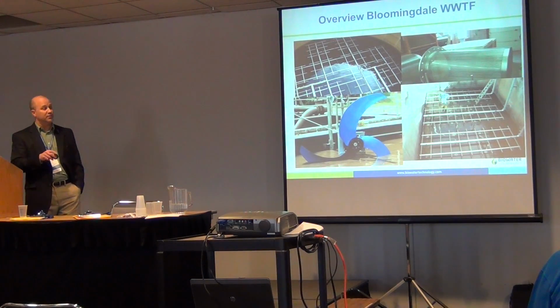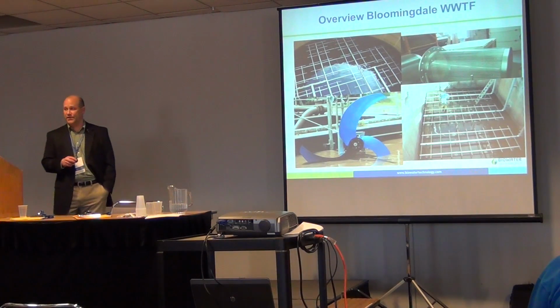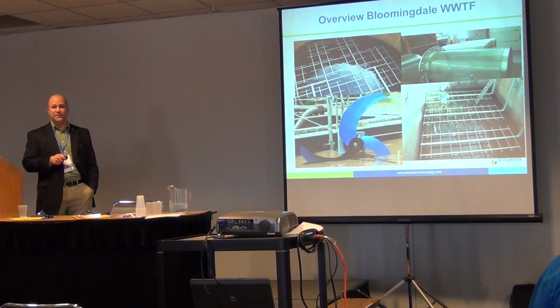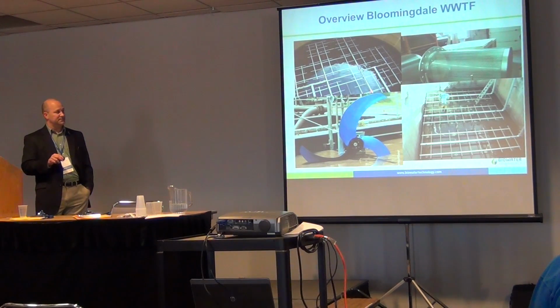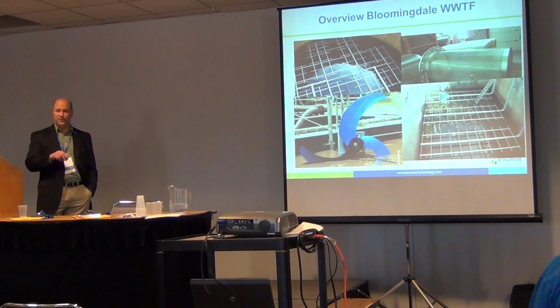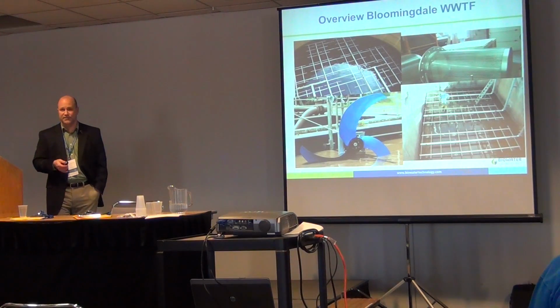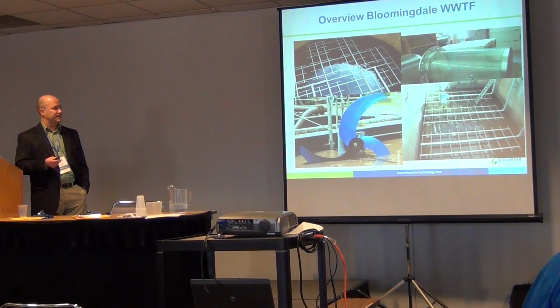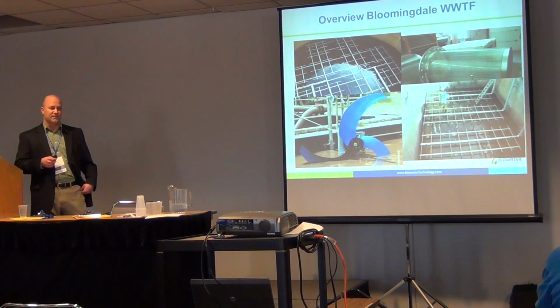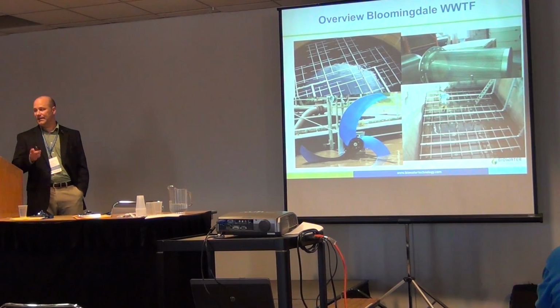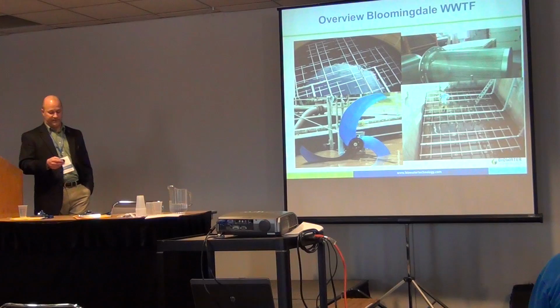You can set up these systems, although this presentation is set up around it, for anoxic zones, where you can do denitrification. So much like an activated sludge system, you can set it up so that you have pre-anoxic zones, post-anoxic zones, depending on the situation. We use a banana-style submersible mixer, very low speed so it doesn't chop up the media. And the newest technology that's coming out for moving that a lot more energy conscious is the large bubble geyser style pumps, where they create those large bubbles that have very low oxygen transfer but great for mixing a tank. So that's another way you can do an anoxic zone.